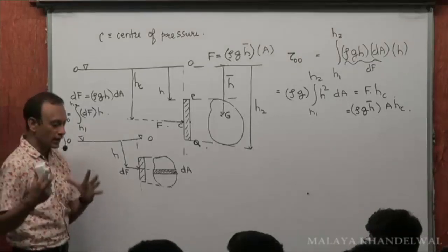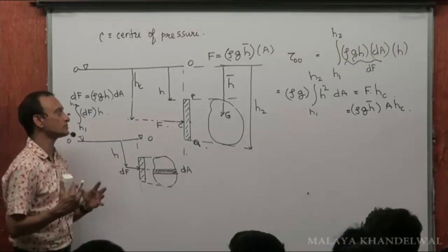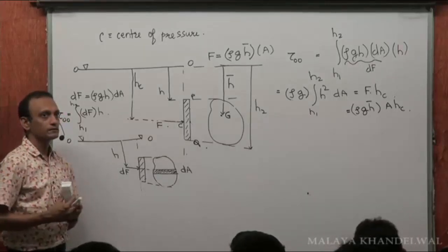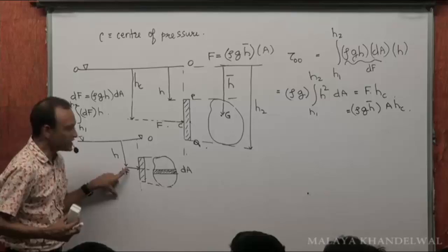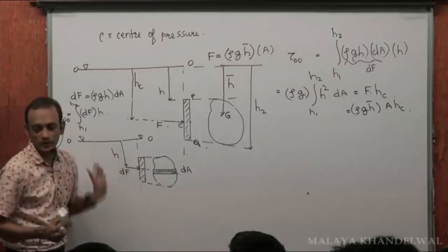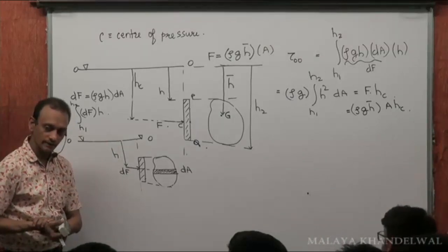See, again, don't get confused. All that I'm saying is, these various dFs acting on this submerged surface will produce a torque about the free surface, right?